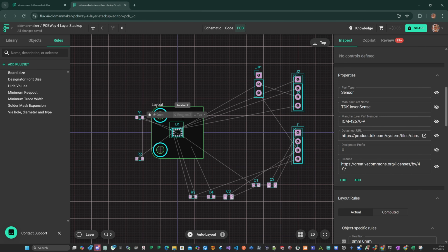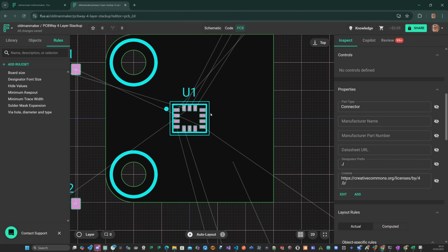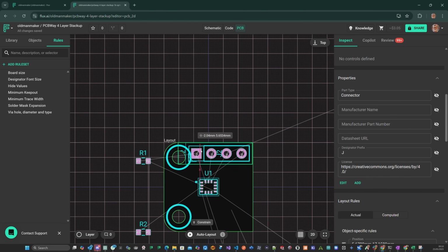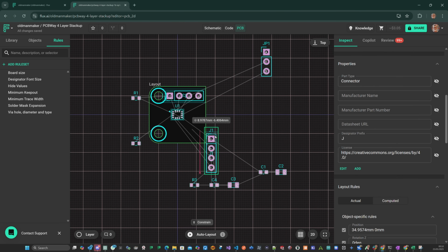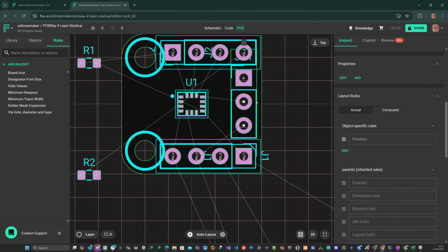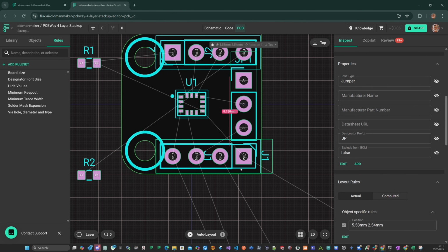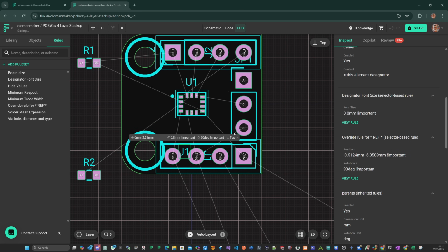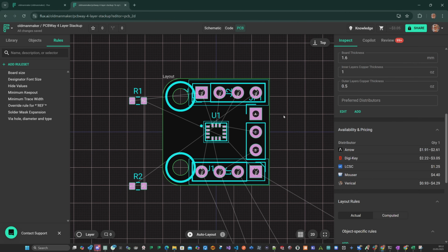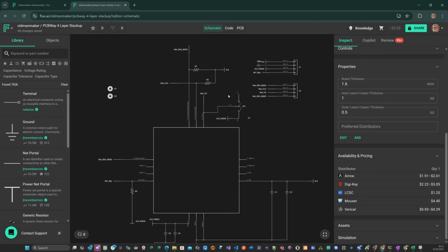In this particular board, the pin headers are going to create the maximum amount of space I have on the board to place components. So I'm going to get them located as well, although I can move them around and finalize them to suit as we go. Next, I'm going to go back and forward between the schematic screen and the PCB screen.